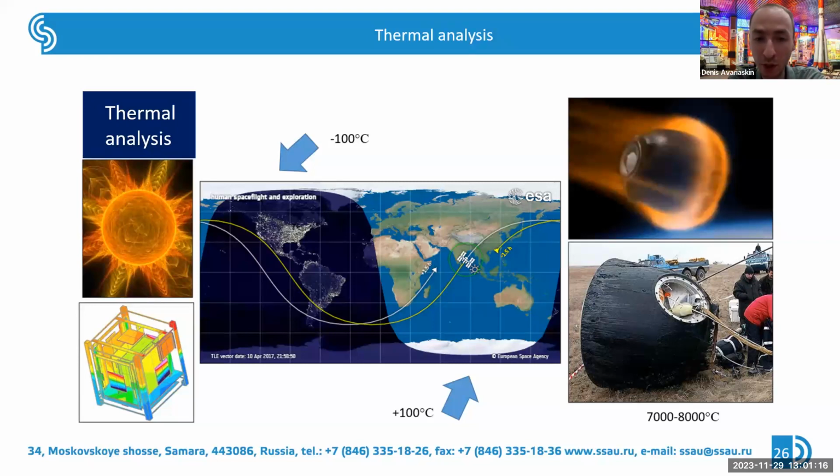And during this 1.5 hours, the temperature can go up and then down, up and down. And this is not very good for the structure or for electronic systems, so we need to make a thermal analysis to estimate if our subsystems will work in these conditions.